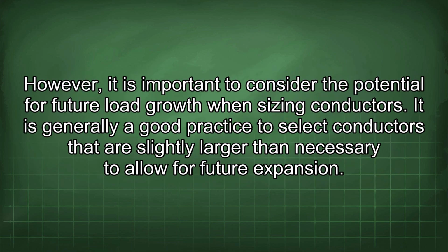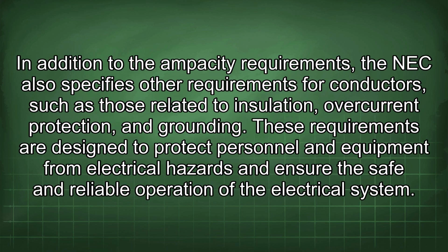However, it is important to consider the potential for future load growth when sizing conductors. It is generally a good practice to select conductors that are slightly larger than necessary to allow for future expansion. In addition to the ampacity requirements, the NEC also specifies other requirements for conductors, such as those related to insulation, overcurrent protection, and grounding. These requirements are designed to protect personnel and equipment from electrical hazards and ensure the safe and reliable operation of the electrical system.